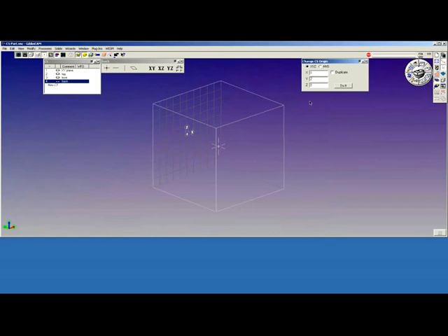Now this coordinate system that we just created has moved to the back of the cube, showing me the markers in the center, but the polarity of the coordinate system is incorrect. If I was to leave this coordinate system as it stands, draw geometry on it, and try to machine it, my cutter would try to go through the part to get to that geometry.